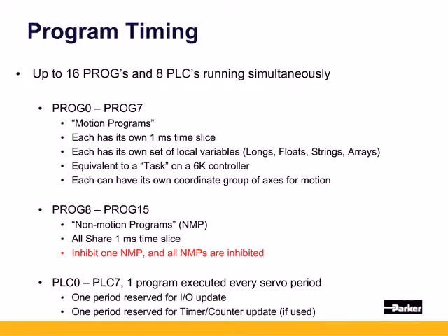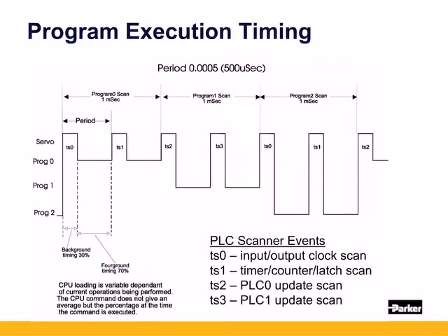For the AcroPLC programs, one PLC is run every servo period, plus one is reserved for I/O update. Another period is reserved if any timers or counters are used. Let's take a look at an example. This example gives a brief description and shows the timing execution in the ACR multitasking environment.